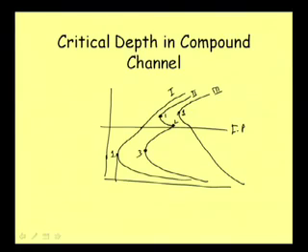For all these, specific energy is of course minimum here in case 1, specific energy is minimum for 2 cases in case 2, but for one case specific energy is not even minimum. So these sorts of different conditions we can have for computing critical flow in a compound channel.